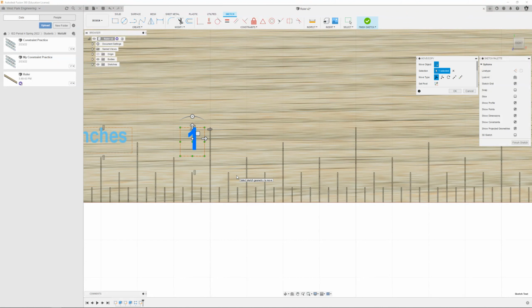And then you got this number here, and I can use the arrow and drag it over and send it right there. And notice how far I'm dragging it over. I want to drag it exactly 1 inch. And you'll see it snaps every 0.05 or 0.1 inches. Get it to exactly 1 inch and then just hit OK. And then now you made a copy.